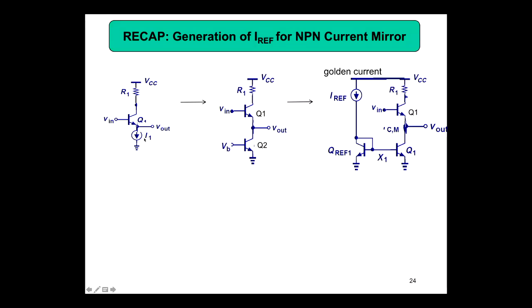And then you use the current source, because in order to bias this one, we will be using the golden current. If you are using golden current, this is a band gap reference. The band gap reference circuit is only one circuit, and that will connect to your VCC here, and from that you will get the golden current. Then you make a current mirror, and that current mirror will be used for biasing this current source. So now you have got an emitter follower biased with golden current. So that's how we will be doing it in the chip.